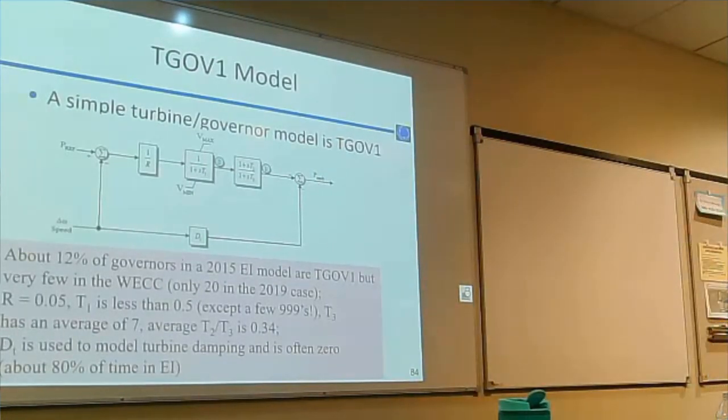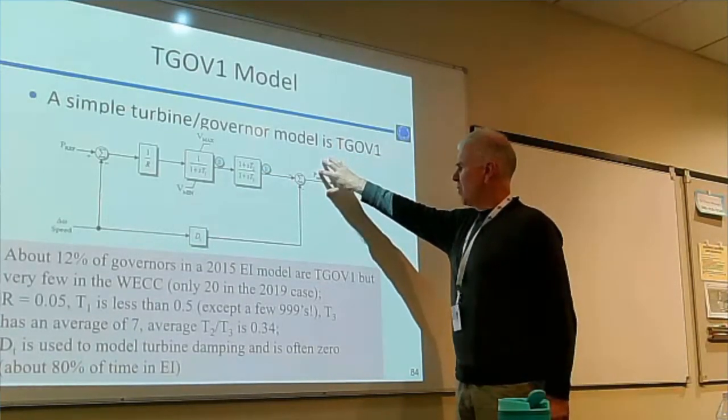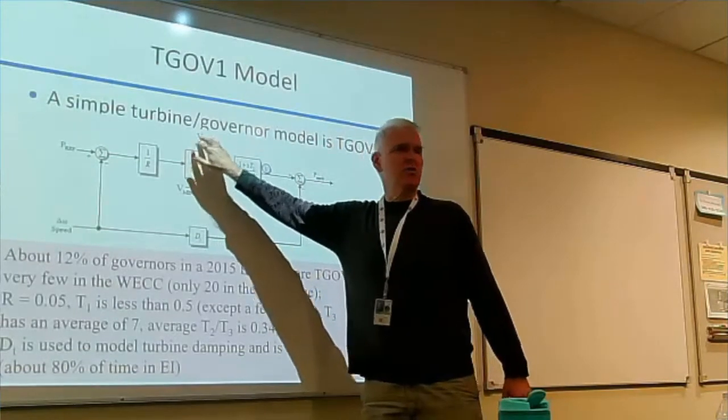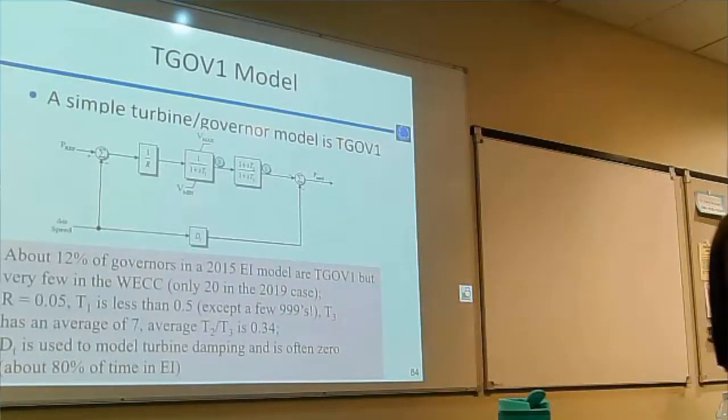This would be a case where initial limit violations could cause problems. That's the most common example. It's the most common example because if your generator is putting out more power in the power flow than the Vmax value, or less power in the power flow than the Vmin value, you're going to have a problem. And the question is, what do you want us to do? We can't change the power flow output. The idea here is if your power flow is valid, then one of those, Vmax or Vmin, is wrong.